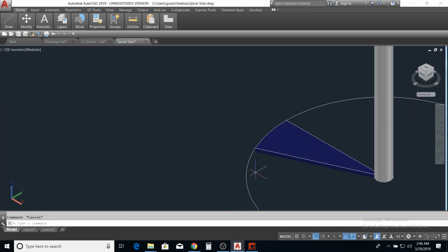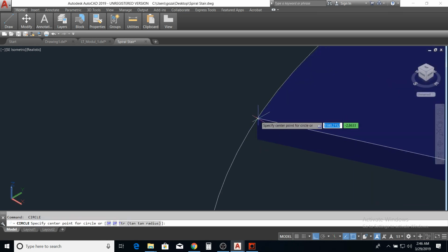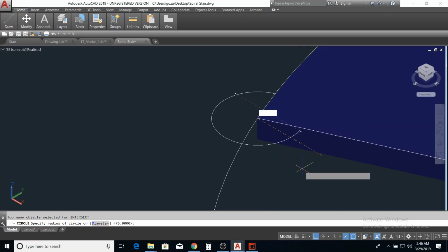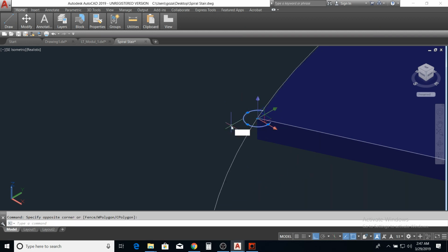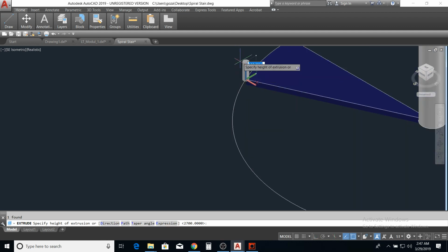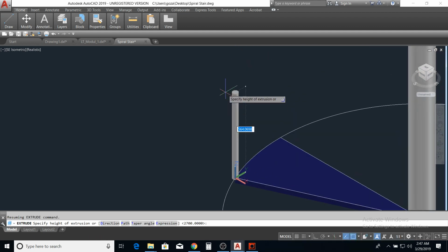There may be a pipe of diameter 100, a pipe of diameter 30 mm. You use that type of handrail, or let's just use a pipe of diameter, let's say for instance, 38 mm at a height of, let's say, 900.